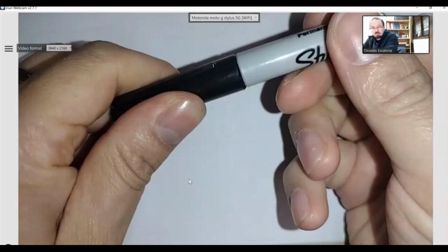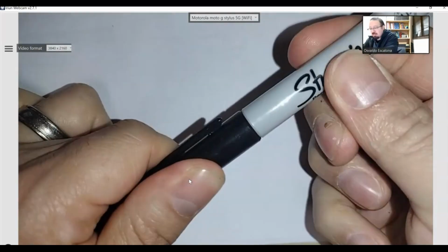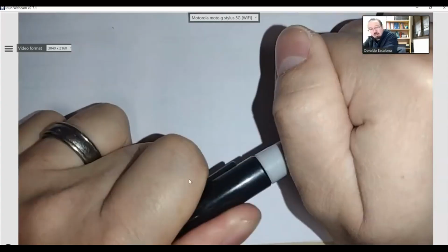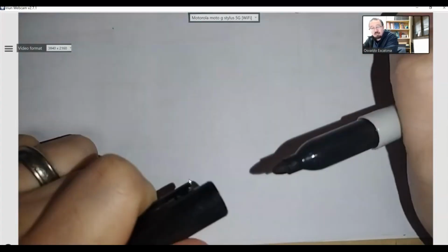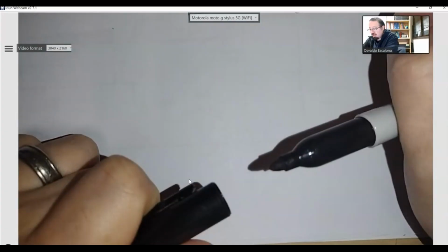Now it is hard to move, right? In fact, it doesn't rotate anymore. But if I were to pull with a little bit of force, it will come off. That is what we call a transition fit.